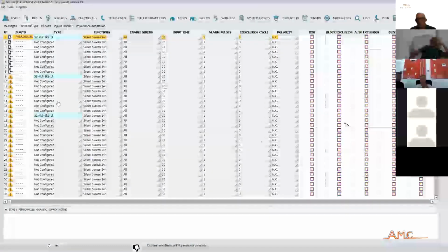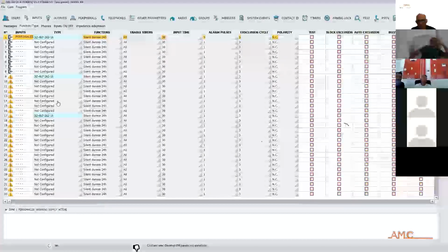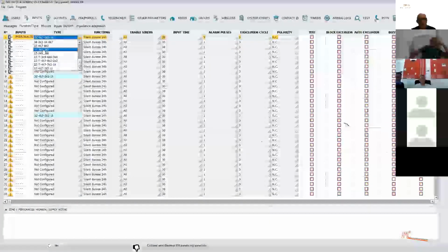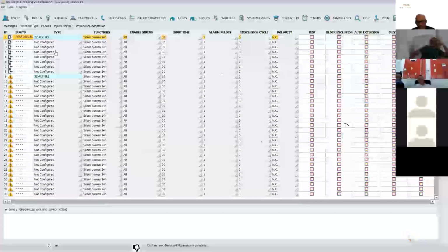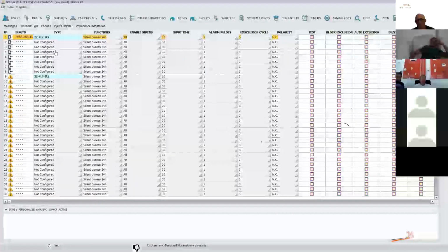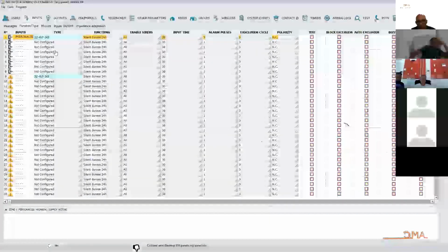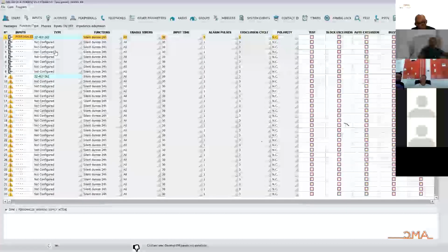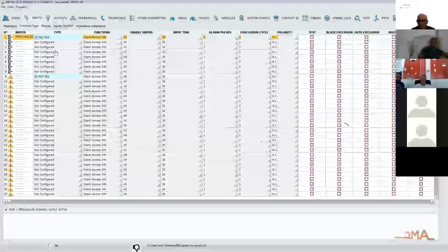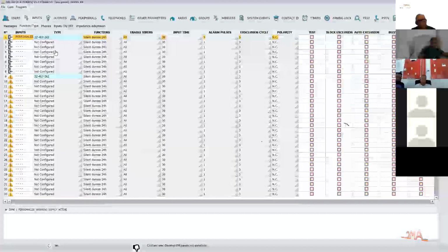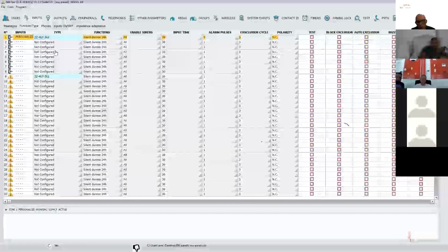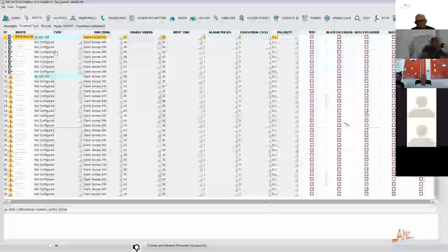It's important that when you use the panel with split zones, with the double zone or triple zone system, the panel does not have the expansion. When you install the expansion of the panel, this feature stops working. When you install the expansion, you need to use only the resistor for the single zone or for balancing or double balance.